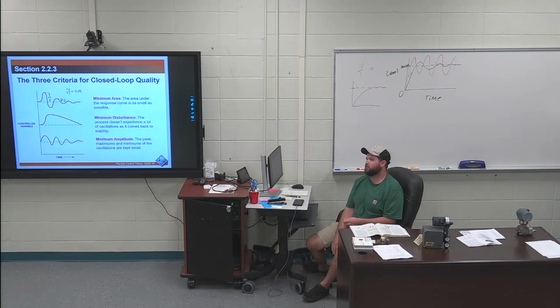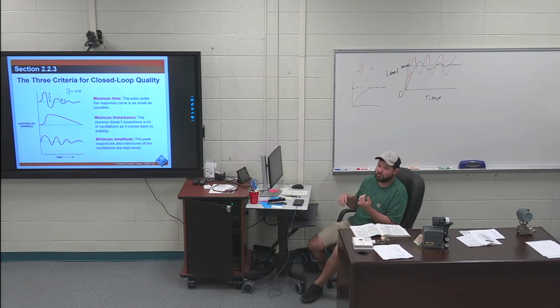So usually for combustion control, you have dampeners for your fuel and your air, and it's essentially how your car works too. Like the mass airflow sensor is seeing how much air is going into your car so it can determine how much fuel to put in your car. And it's an engineered ratio saying I need this much air and I need this much fuel. Whatever that ratio is, you need to maintain that. So if I push on the gas pedal and I open up my throttle body, that's going to let more air into my mass airflow sensor, and that's going to tell the fuel injectors to inject more fuel and keep that ratio the same. Does that make sense? It's probably one of the most common ones.